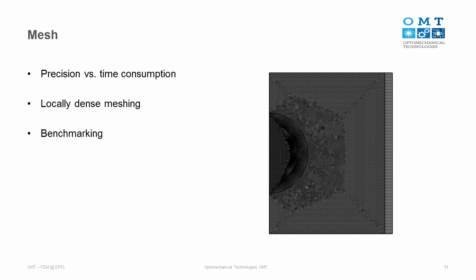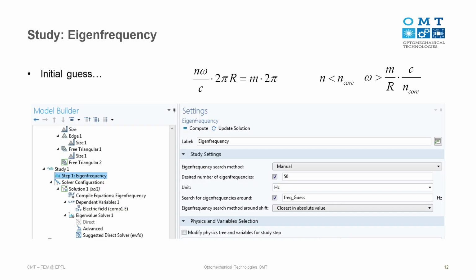And there's also a very important side, like benchmark. So if there's an analytical solution, you need to compare before you really make your simulation in reality. And if there's no analytical solution to support you, then you need to gradually change the level of mesh to be more and more dense. Eventually, you can find the overall solution is convergent. Then you say that okay, I'm okay on the mesh level. So that's the idea of benchmarking.